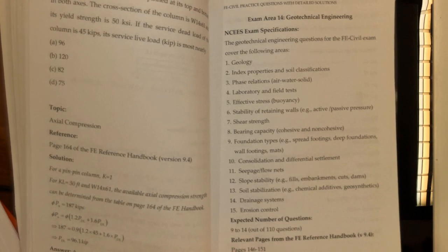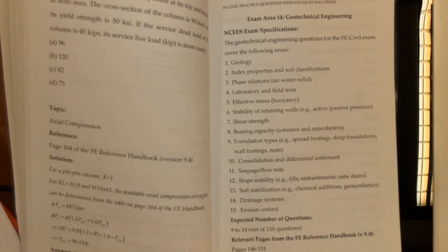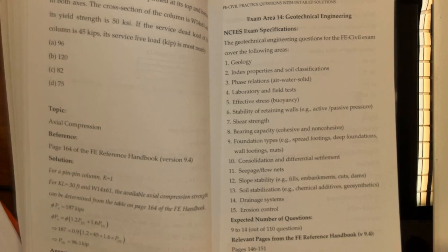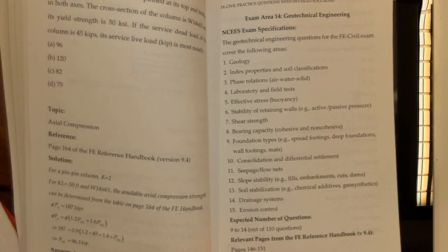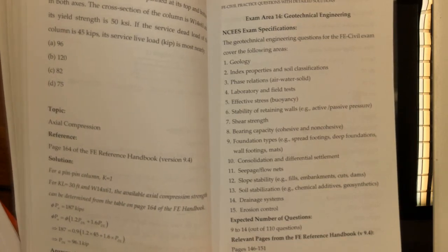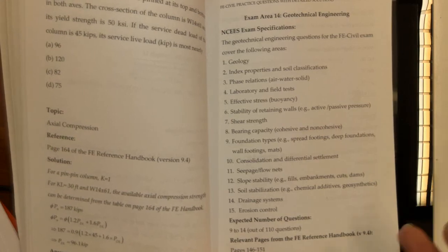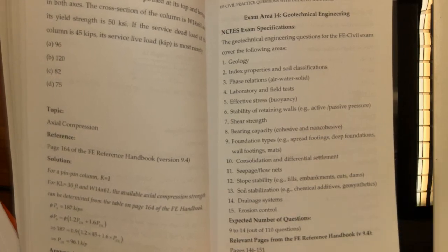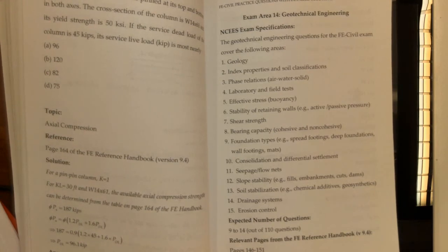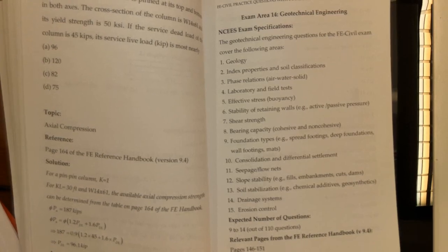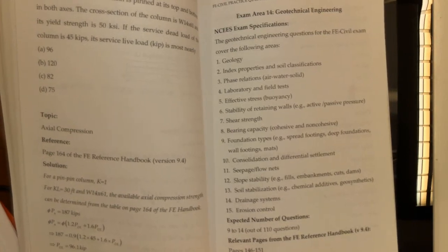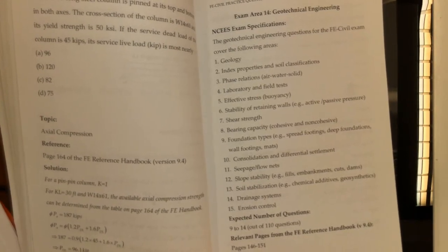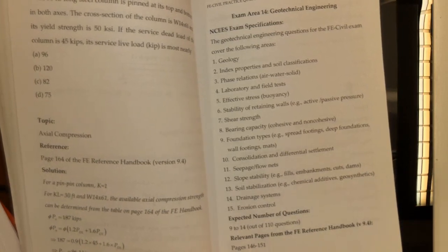Shear strength, we looked at a couple examples of what I think they might ask for that, and that's, you know, given a normal stress and a shear stress, find something else. I guess they might give you a cohesion, so that would be a difference versus saying the test was done on the sand and recognizing that cohesion is 0 in that case. But the kinds of things that they're asking there are probably find the angle of internal friction, or for a given angle of internal friction, what is the shear stress at failure? So that's the kind of thing to expect.